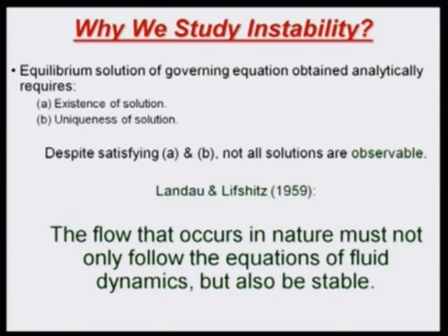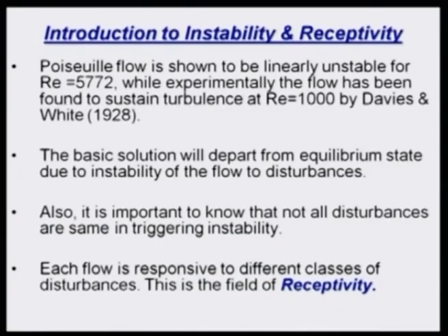So, this was the nonlinear aspect, which was later found out when linear stability theory was developed, that pipe flow indeed remains stable to linear growth of disturbance modes. So, that is also true for Couette flow, that Couette flow and pipe flow remain really stable for all Reynolds numbers.